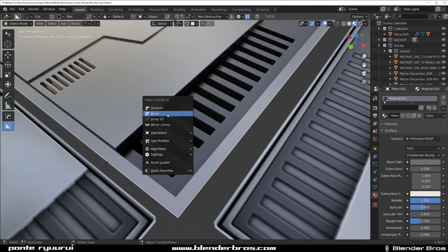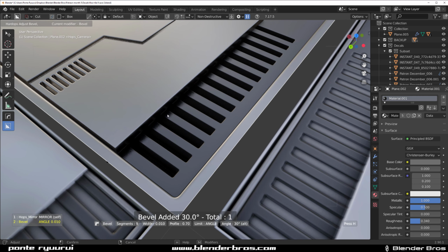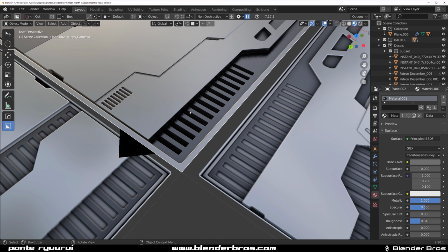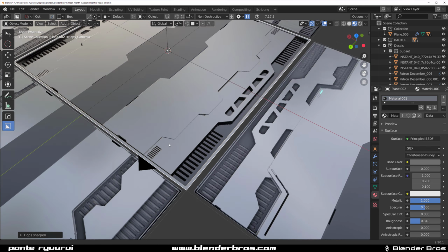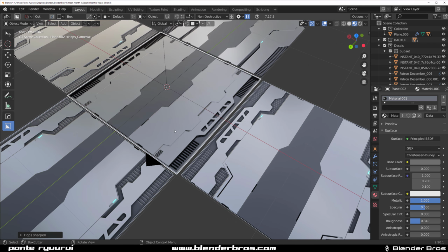So QB, go to 9. You need really smooth bevels for decals, yeah. Don't be stingy on bevels, because remember, geo count doesn't matter because you're gonna be baking this anyway, so no one's counting, yeah. It's all about quality for this one.